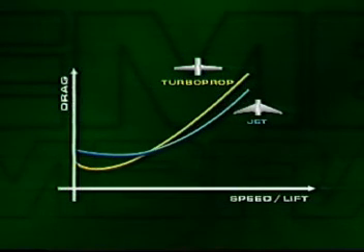This is valid for both turboprop and jets, with the exception that the speed at which this effect begins is much higher in jets. Moreover, in turboprop aircraft, this speed is well identified by the steepness in the drag curve, but it is quite flat, extended on the jet's curves. I just want to show you that if you allow the airspeed to decrease below the minimum drag point, the aircraft will quietly slide to the backside of the curve, and the jet does not produce noticeable changes in flying quality. Don't get caught by the situation.